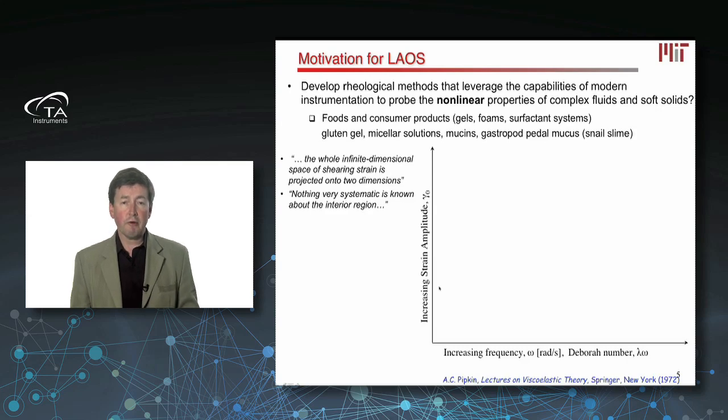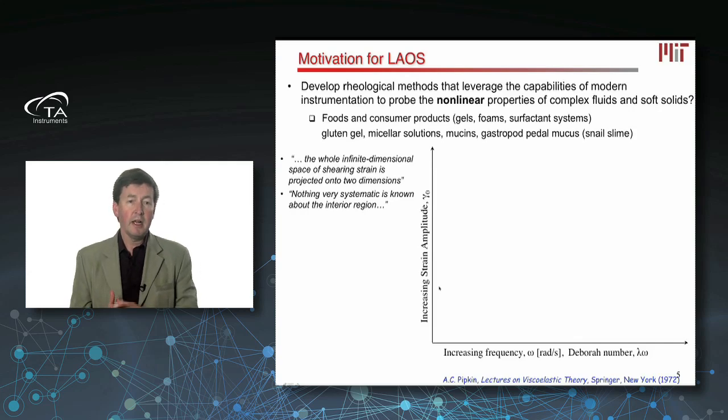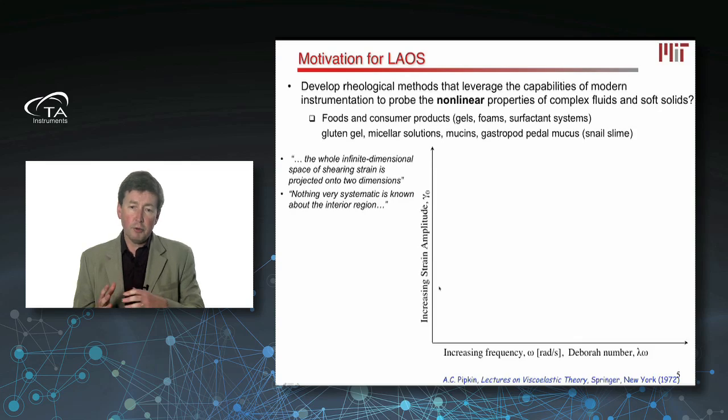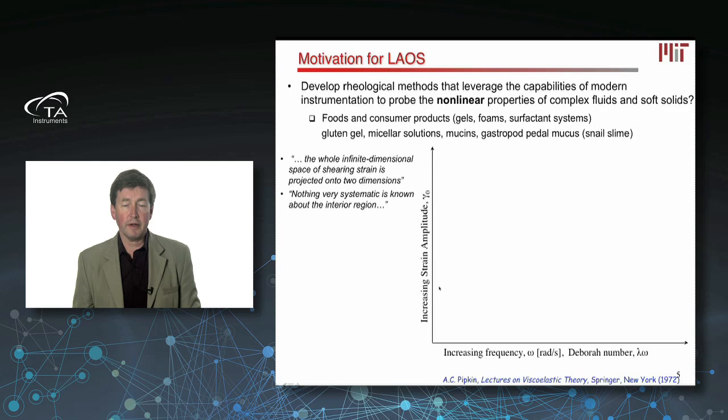I'm going to introduce to you a framework to do that that's really described by a guy called Pipkin back in the 1970s. The plot that I'm showing you is a two-dimensional plot that I call a Pipkin diagram. On the horizontal axis is frequency. For those of you who know how to do frequency sweeps, that's a very simple test to do, where you load your sample into a rheometer, and then you progressively increase the frequency as you move towards the right of the curve here.